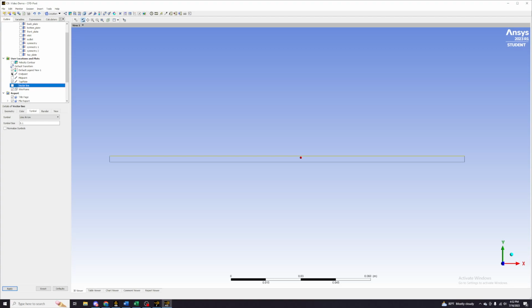Next, what we'll do is we want to see the boundary layer velocity profiles. We wanted to see it at the endpoint and the midpoint. So I created the endpoint and midpoint here, these two yellow lines. The midpoint, since this post is in meters, I had to do the unit conversion from inches to meters.